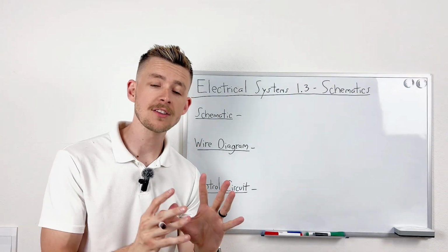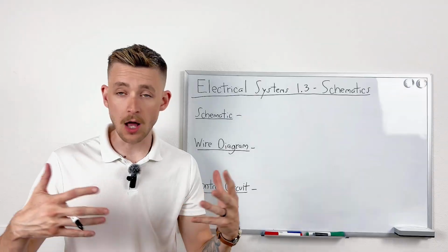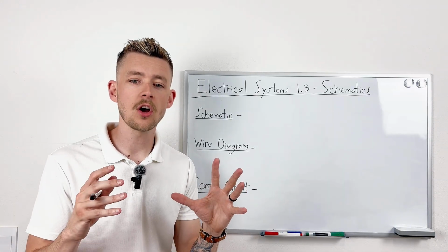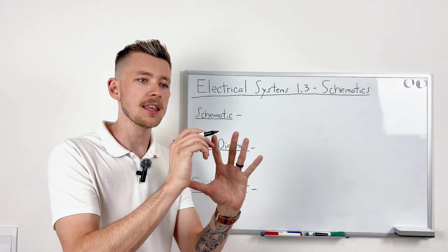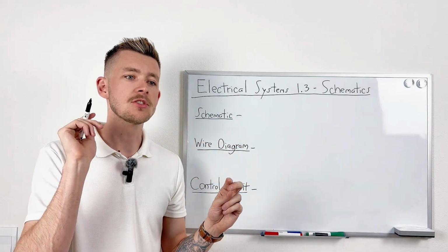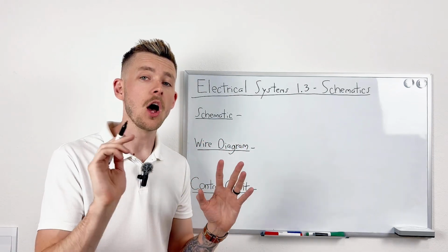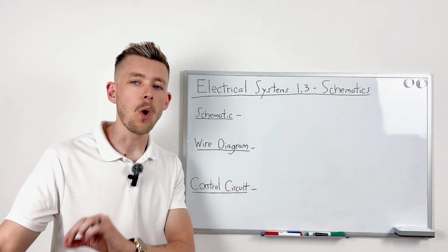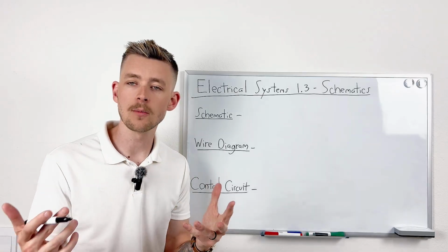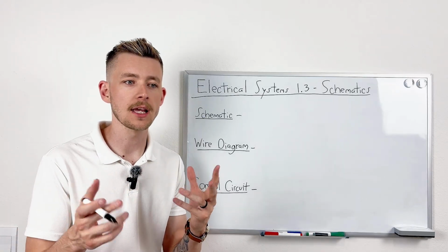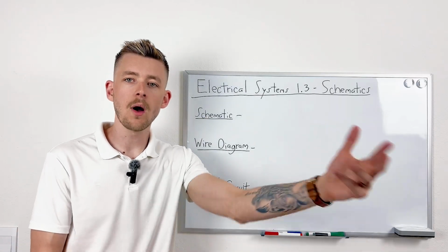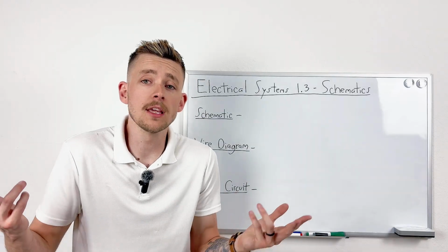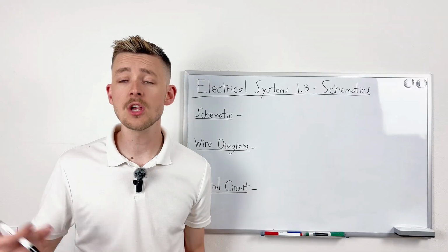Now, when it comes to wire diagrams, this is actually going to be the specifics in the current flow and what it's going to be going through when it comes to switches, but also diodes and resistors, and transformers. Basically, the wiring diagram is going to be the direct path of the wires. So wiring diagrams include the specific wires that are associated and the terminal configurations, as well as your termination points, where your wires are going to be landing, and which wires to check if you wanted to test the continuity between a switch and a motor.